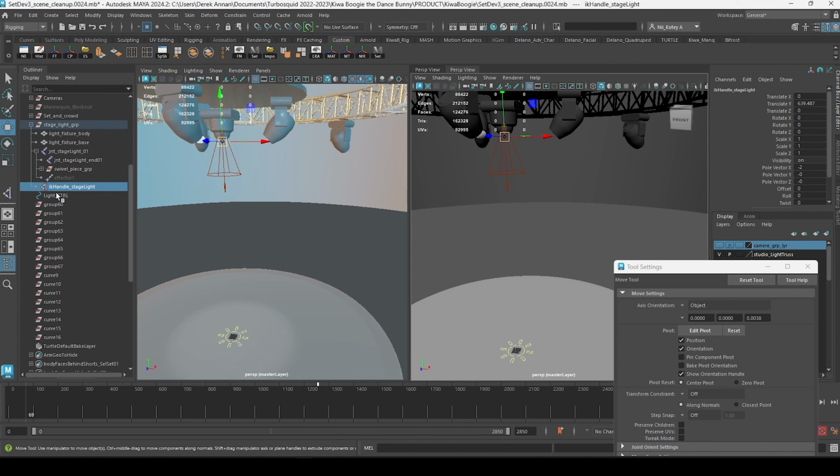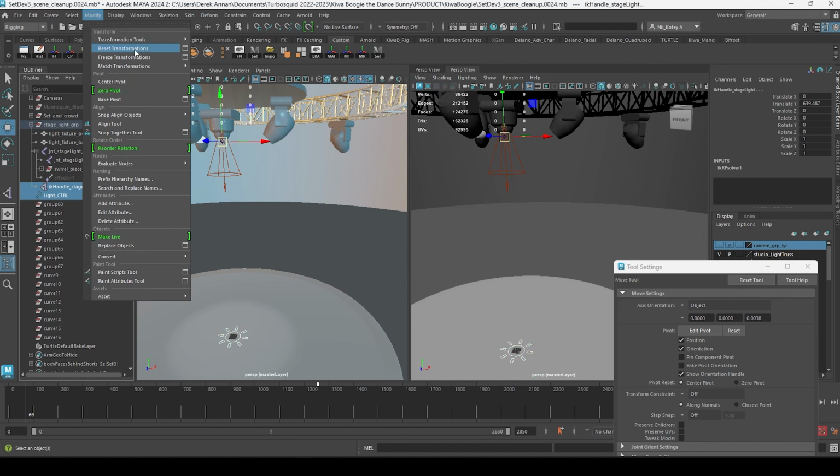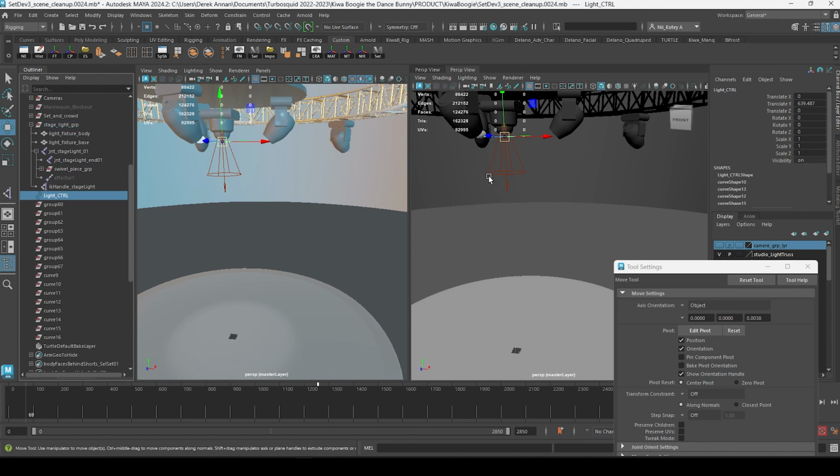All right. Now I'm going to make sure that I don't get a pop when I connect this IK handle to this control. So I'm going to select the control, select the IK handle, and go Modify, Match Transformations, Match Translation. I could have just done it in the two axes that I needed, but this is fine too. So I'll just now select the light now that I know it's snapped perfectly, and I'll move it down. Select the control and move it down till it's back on the ground, and now I can freeze transforms on it in preparation for a point constraint.